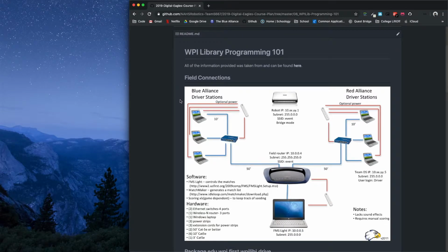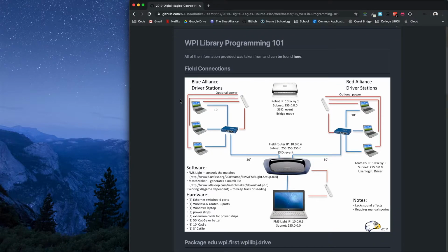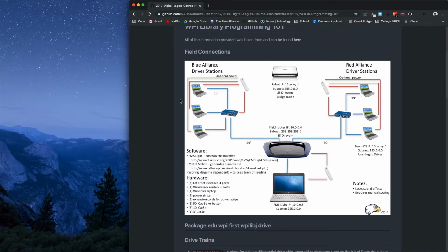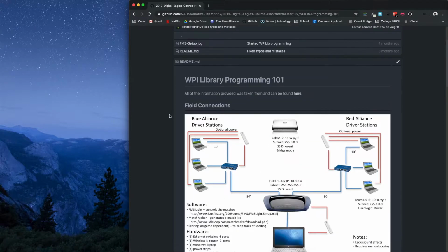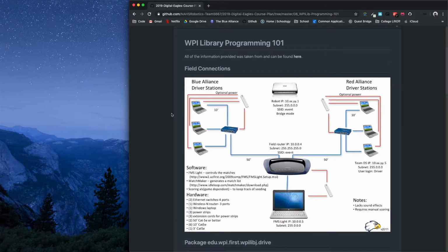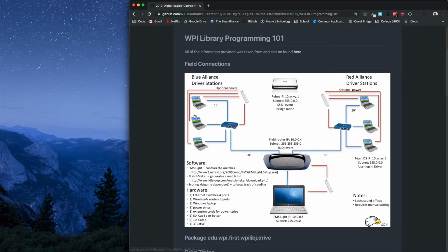Today we're going to be talking about the WPILib library and how we can implement hardware. Everything that we need in terms of hardware is all in the WPILib library, unless we're using some sort of software that isn't supported by it, but most of everything that you'll need is there. One thing that probably isn't is the NavX, but that's something that we can download as a dependency and then of course implement.